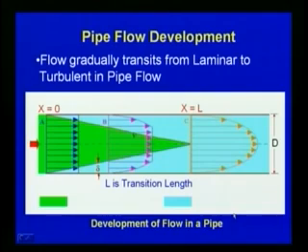So, if we further analyze the pipe flow, we can see that depending upon the flow condition, velocity and other parameters, if the flow starts laminar, then depending upon other parameters, the flow gradually transitions from laminar to turbulent. Here you can see the boundary layer development, and at this stage we can say that the flow is fully developed into turbulent. As far as turbulent flow is concerned, the velocity variation is like this. So, here the flow is fully laminar, and here the flow is fully turbulent.